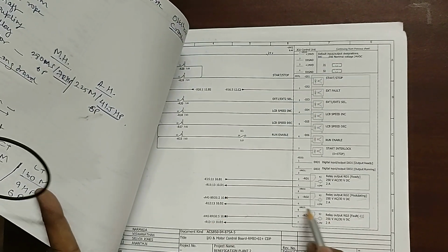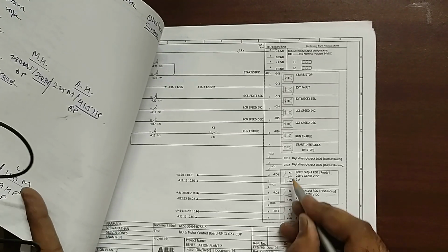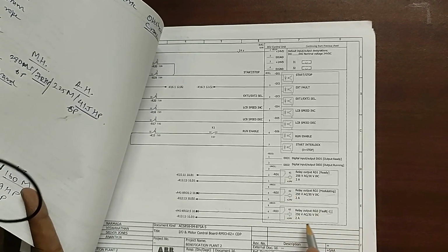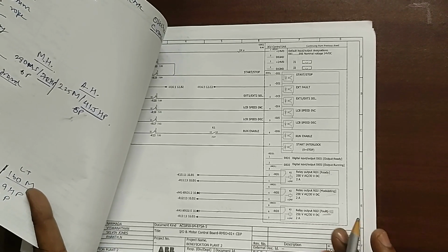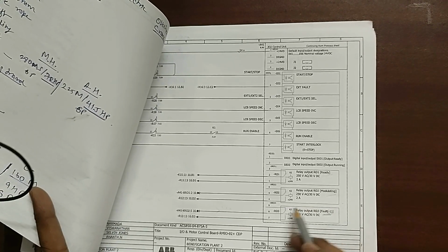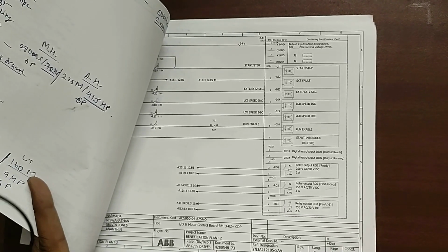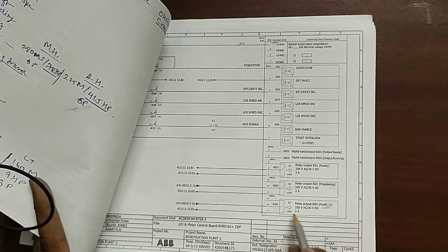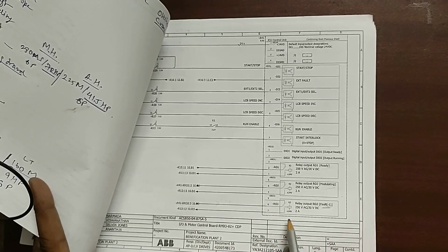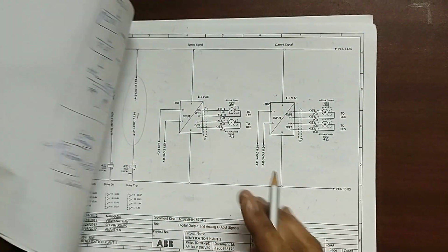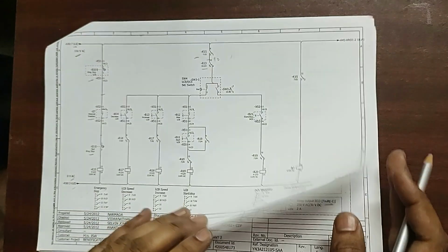Here it is. So this should remain in open condition. There is a small relay inside this, that is K1, K2, K3. This is the drive's internal relay, and that works on plus 24 volt. So whether the drive is in fault condition or not is decided by the panel setting. If you go through the settings, that video is also available in the playlist. There you can select this setting as fault or fault minus, and here it should remain open. Since it will remain open, it will not get supply. That 110 volt won't come here, and this R13 won't pick.